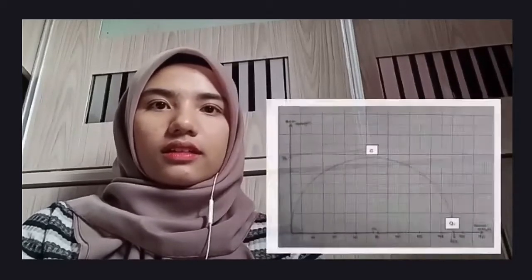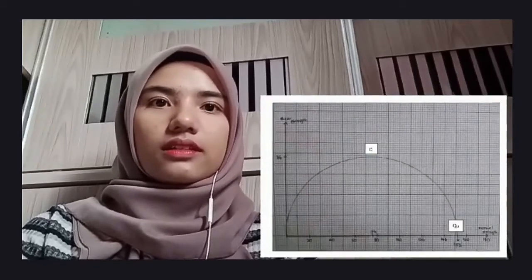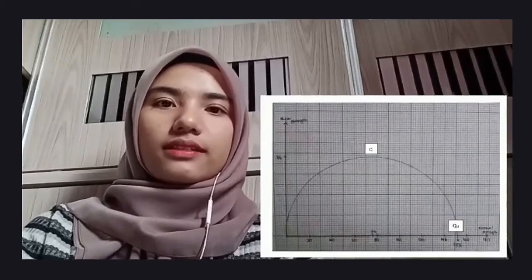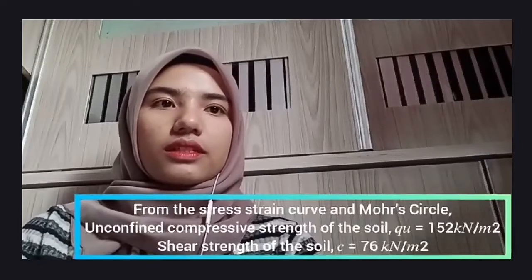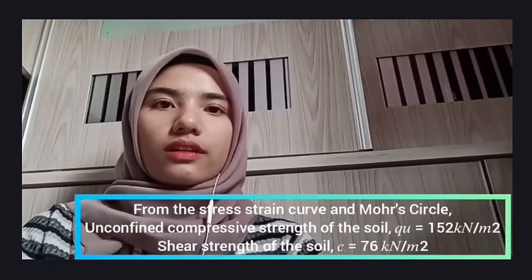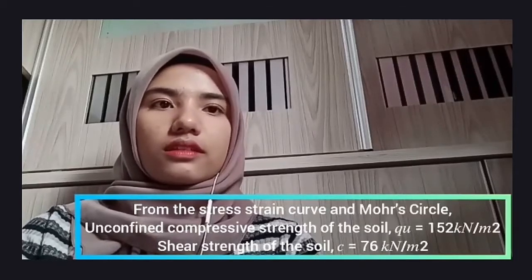And the Mohr circle for the specimen is shown. From the stress strain curve and Mohr circle, we can determine the unconfined compressive strength of the soil, which is 152 kilonewton per meter square, and the shear strength of the soil, which is 76 kilonewton per meter square.